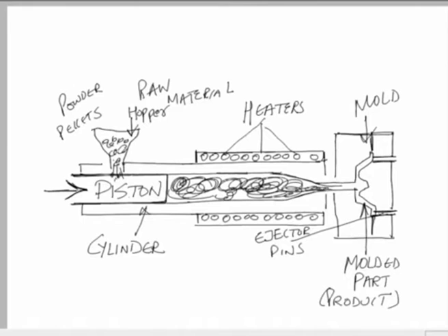the heated plastic which is going to come and enter into the cavity which is generated between the mold, and we have the ejector pin. So heating is there, forming is there, and finally the cooling is taking place. Now the diagram as a whole is complete.